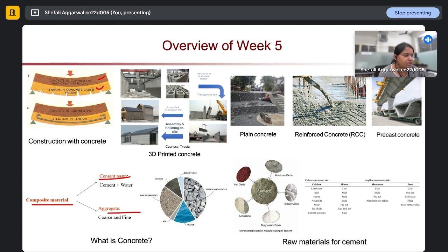So next, now that we understand what exactly concrete is, what are the different types of concrete which we are dealing with? First is plain concrete. We use plain concrete in structural elements which do not take up loads, mainly things like roads, a park area, or a stairs area where there is no provision for taking up the loads from the superstructure.